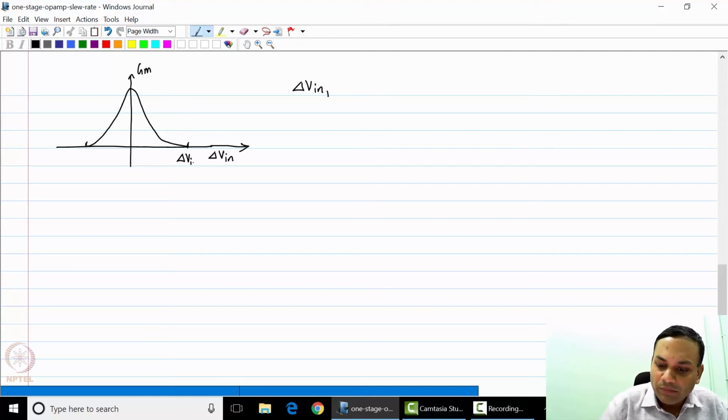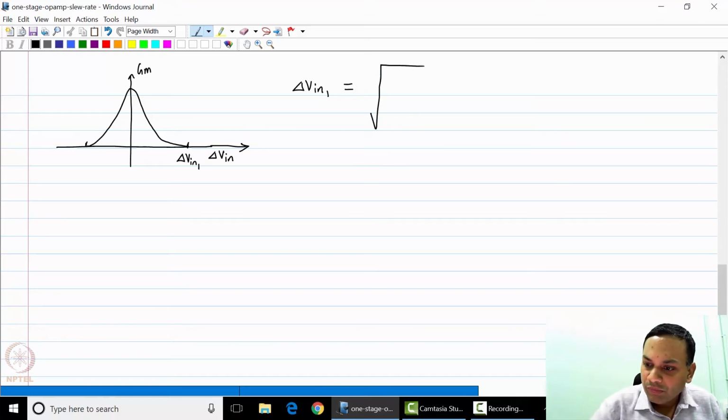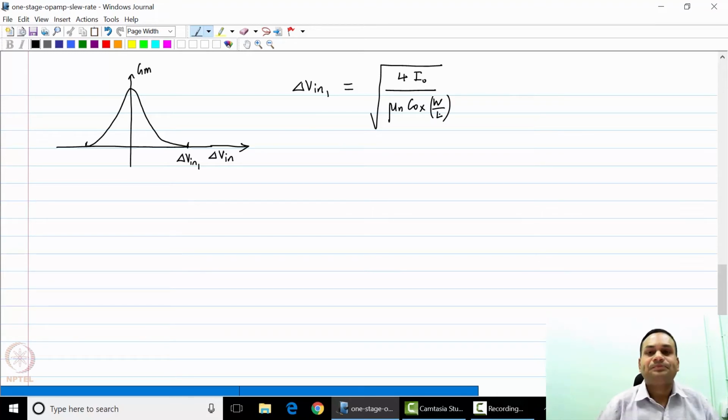I'll call that delta Vin1. This delta Vin1 happens to be equal to root of 4 I naught over mu1 Cox W over L.